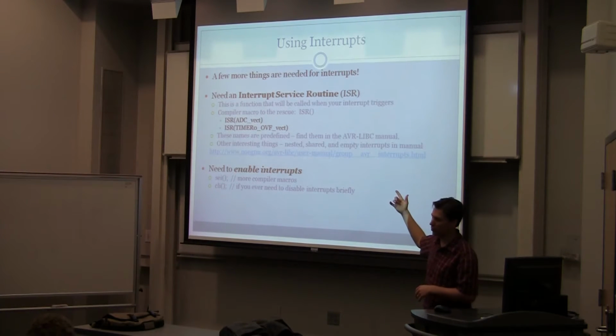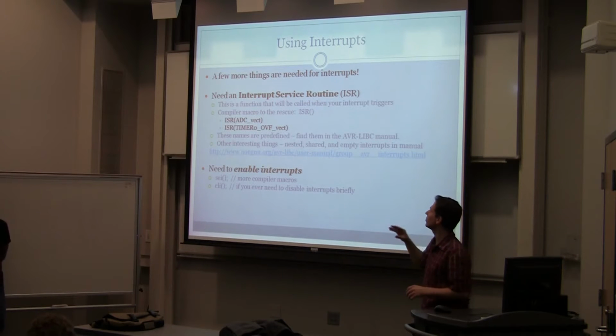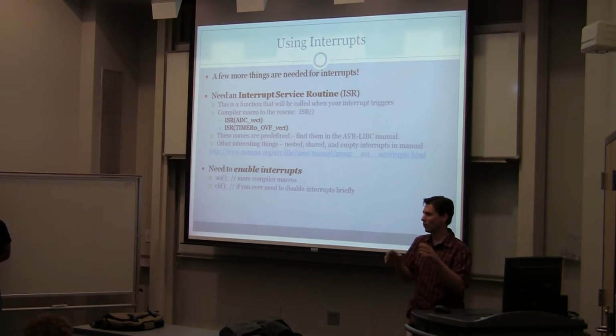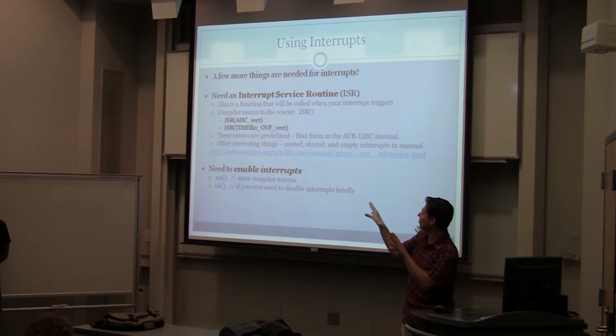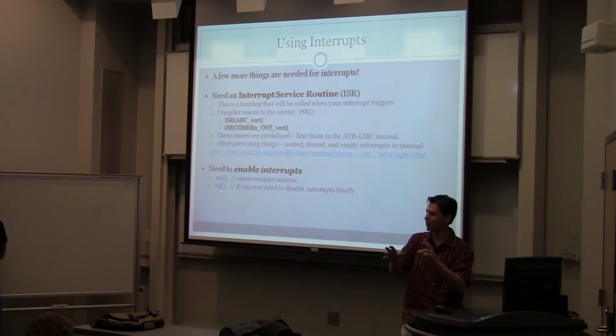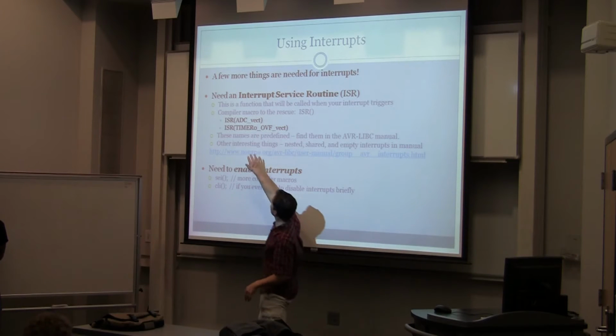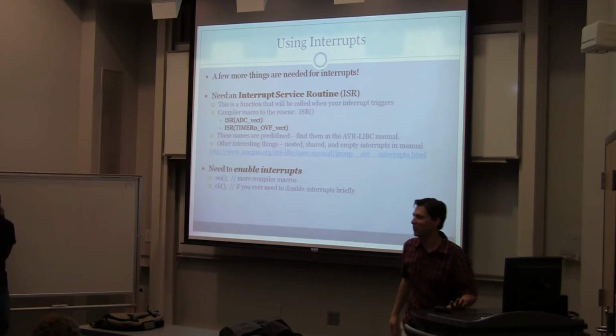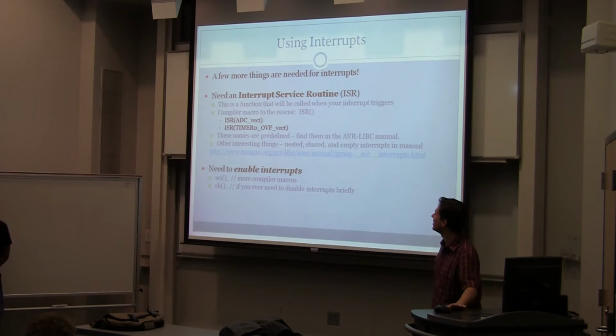So you saw the ISR function, so you need to define one of those. If you enable an interrupt and you don't have an ISR, an interrupt service routine, that matches that interrupt, and it matches it based on these wonderful codes that are defined in some obscure document that you should have a link to, but which we'll definitely link for the next assignment where you're actually going to need interrupts.